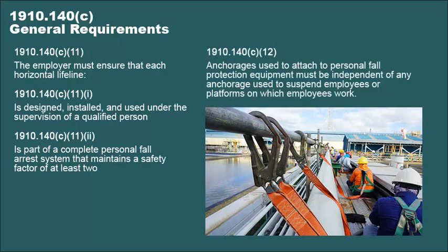Anchorage that is used to attach to a personal fall protection system must be attached to an independent platform, and this independent platform must be able to support 5,000 pounds, or if they are on a mobile platform, they should be attached to the center of the platform.